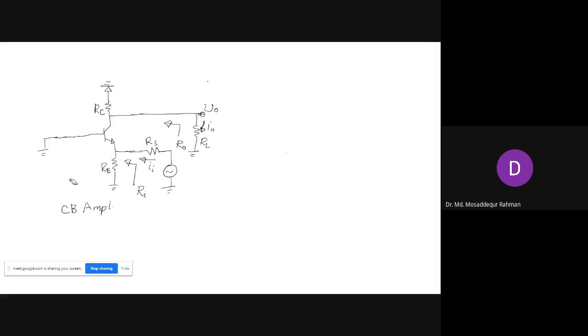Okay. So that is how it's done now. Let's see, the base is just grounded, right? Connected to ground. So that's the common base. Now the input side is okay. So this part, the input side, right? We see that we can again apply the Thevenin's theorem here and replace the circuit by its Thevenin's equivalent. So let's do that.